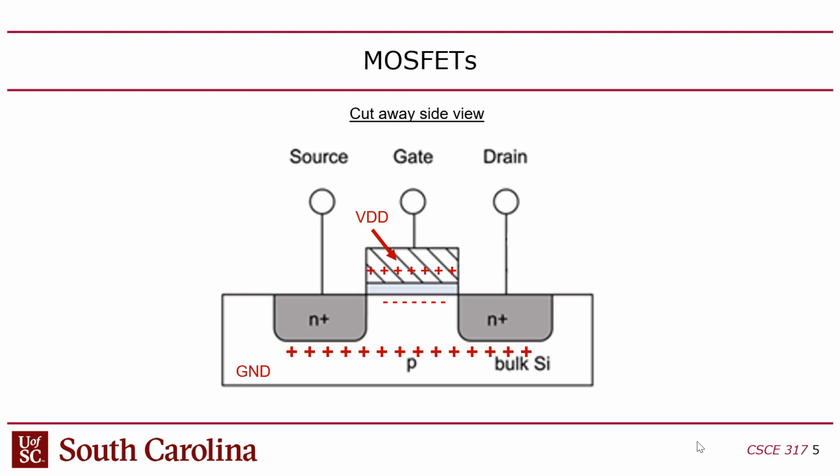But then you might say, okay, well then what's the voltage over this capacitor? Well, now we don't know anymore, because when you bring these charge carriers up into the channel, it decouples the channel from the substrate. So what ends up happening is that when current starts flowing from drain to source, which is one diffusion area to the other, the voltage on the bottom plate of the capacitor is actually a gradient that starts at the voltage of the drain and ends up becoming towards the voltage of the source, right? So really what you're looking for here is what is the average voltage between the gate and the channel? So the capacitor is an average voltage over the capacitor.